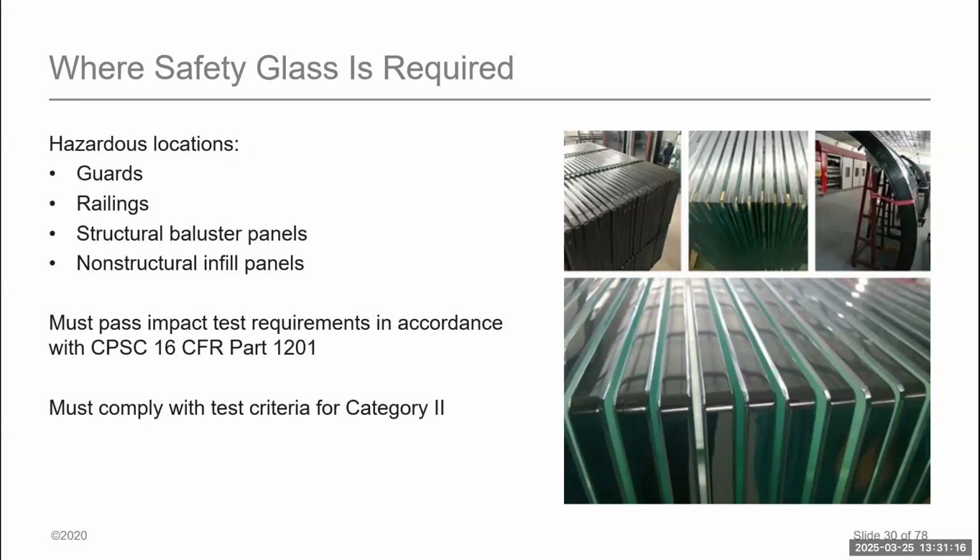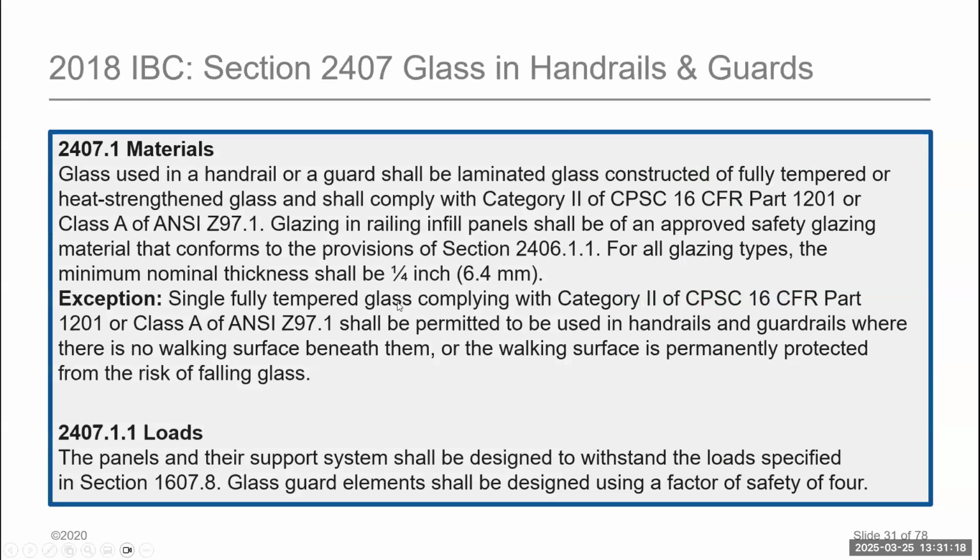That fabricator is going to transform that plate glass into the safety glass that we need to incorporate into guardrails. So let's talk a little bit about the minimum requirements of what we need in glass. The first of those is the glass needs to be a minimum of 1/4 inch thick, and that is 1/4 inch thick when it is incorporated into a laminated piece of glass. I don't think we would ever see a 1/4 inch thick work even for a glass barrier. It's going to meet a certain set of testing requirements, ANSI Z97.1. Again, this will be handled by the plate glass manufacturer themselves.